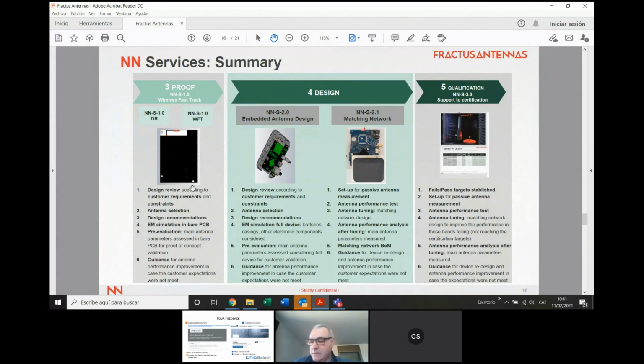Lou is asking the question, is saying that the external housing shall also play a role. Testing should be done in a complete housing. Is it also possible to use a metal housing? In some cases, it is possible. You only need to take some precautions in the distance between the metal and the antenna location on the antenna PCB.